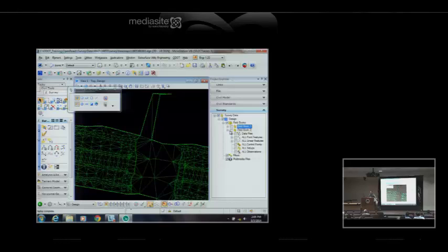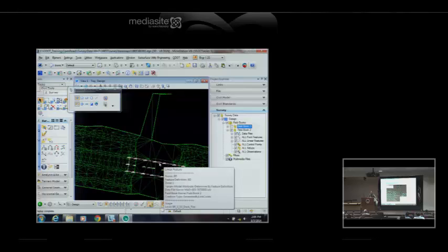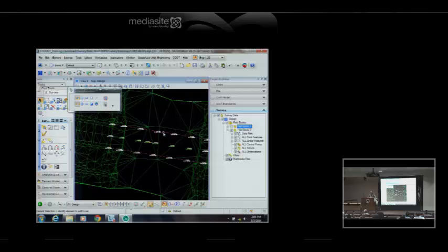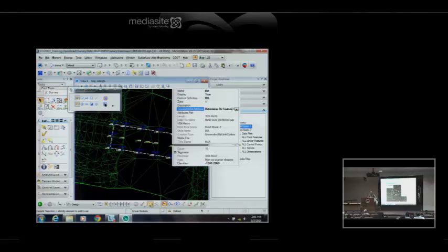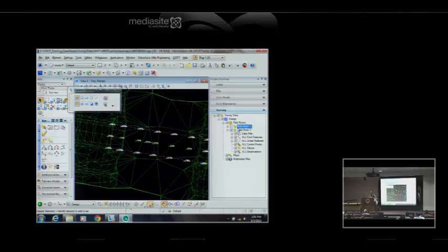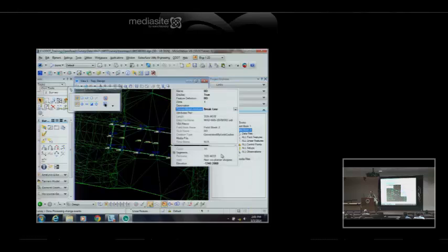And the second one, okay, this is not a feature that is included in the DTM by default. So on this feature, since I want to make a DTM from that perimeter of the bridge deck they surveyed, I'm going to click it under its properties. Instead of telling it the terrain is determined by the DTM, I'm going to tell it this is a break line. And then I'll create a terrain model for that. Separate terrain model, and I will change its feature.